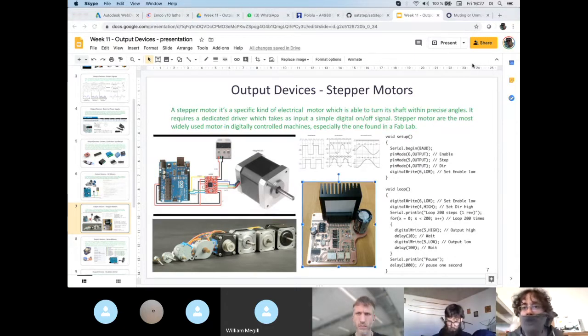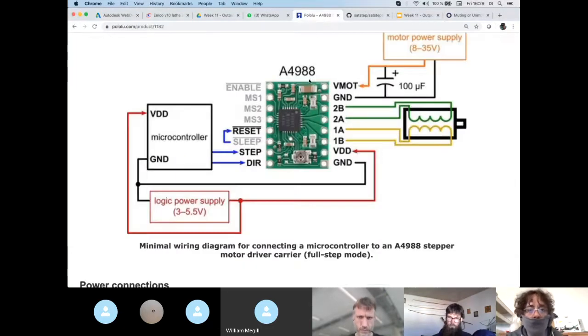So the last thing that you can regulate on the driver from the stepping mode is the current. So you see this little trimmer over here. What you can do is you can rotate this clockwise or counterclockwise to increase the current that you give to the motor. So when you buy a motor, the motor has a certain amount of current that it can take per coil.